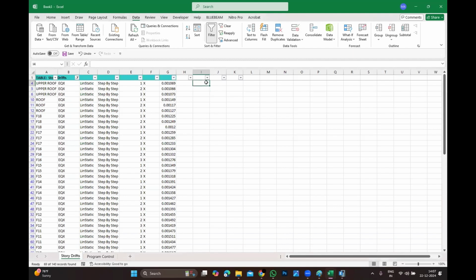So now here, 4 multiplied by, yeah, I was supposed to give you the codal reference. The problem is that in the code it is 4.5. Up till now, the problem is they want us to consider a building frame system, even though it's a combination system. When there is a shear wall, they are asking us to take 5. It's fine, 5 for shear wall system.